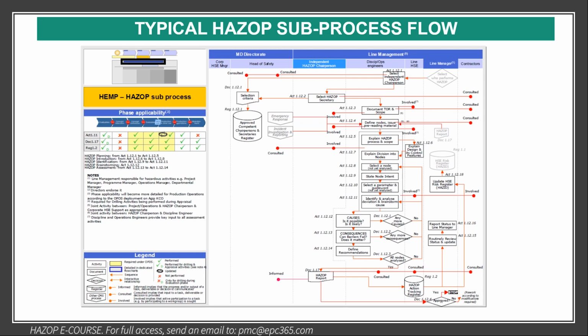for the project. Hazop will be done in different phases of the project. Normally a very simplified Hazop in pre-project, in FEED and detail design. And in detail design, when the P&ID review goes and there is a mature P&ID, then you will do Hazop. And also when you select the vendors, then you will do the Hazop package.